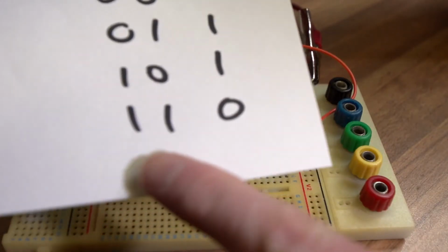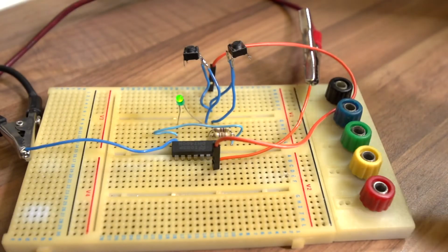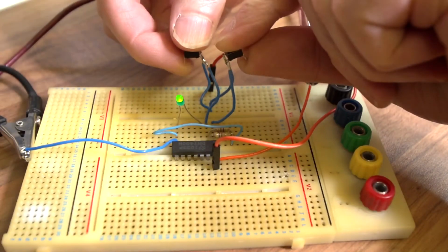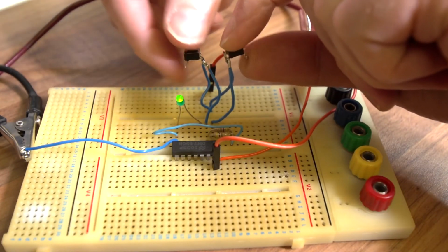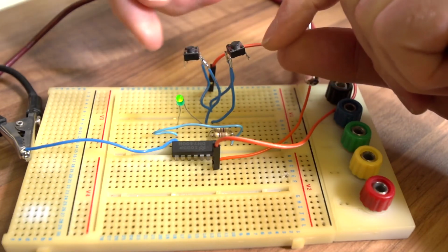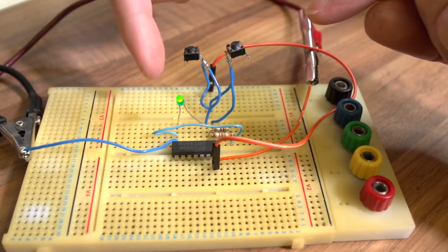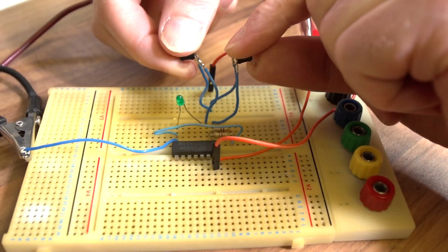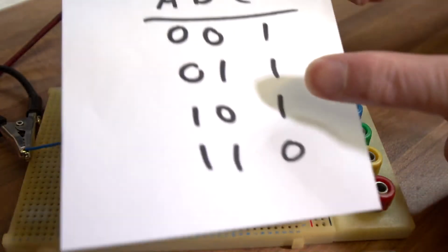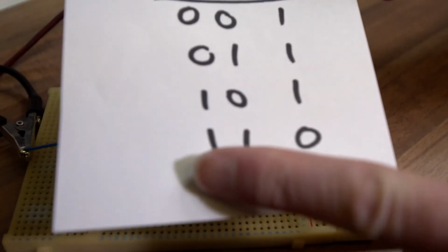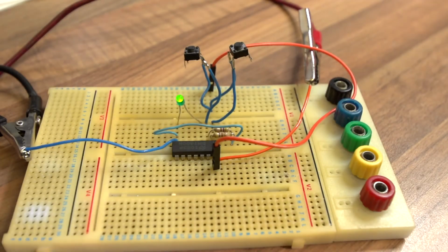What happens when they both go on? Both switches on, the LED should go off. Let's try that. And I need 2 hands for this. Press them both. LED goes off. Leave go of them. So either one of them doesn't do anything, and both off, like right now, doesn't do anything. LED stays on. Press them both. LED goes off. That's exactly right, and that checks with the truth table. Only when they're both on does the LED go off. And that's a 7400 NAND gate.